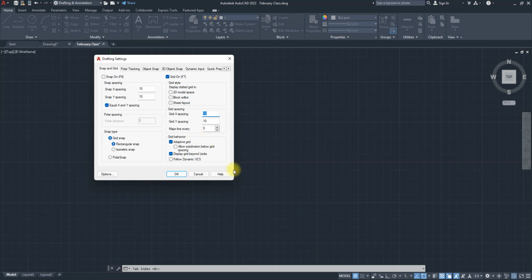All right. And if I want to set this thing, I need to look at the shape I want to create. Now, the good thing with this grid and snap is that you can change it to anything you want at any point in time. I can change this spacing to whatever value suits one particular shape, and for another shape, change it so that it allows me to create that shape easily. So, I want to create this L shape. And remember, from here to here is 8. From here to here is 6. I will know that the smallest unit here is 2.